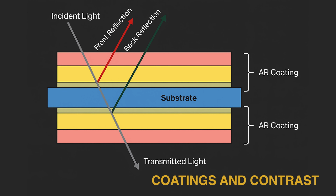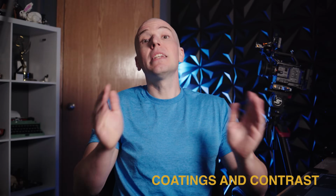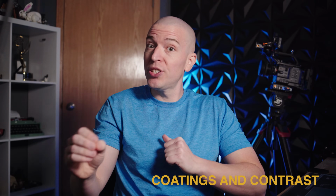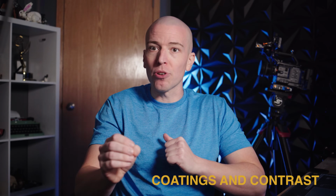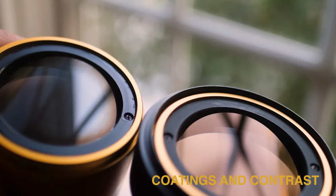Coatings fix this by applying ultra-thin transparent films to lens surfaces. These layers are engineered so reflections cancel themselves out, letting more light pass through. Modern coatings use multiple layers: magnesium fluoride, silicon dioxide, aluminum oxide. Each layer minimizes the reflections across different wavelengths. The impact is dramatic. More light reaches the sensor, blacks stay deeper, colors stay vibrant. At the same time, coatings help protect delicate glass.